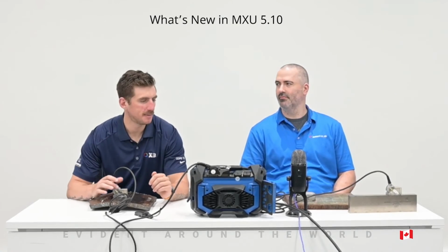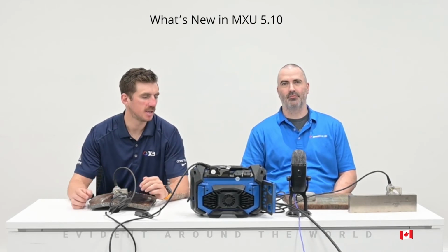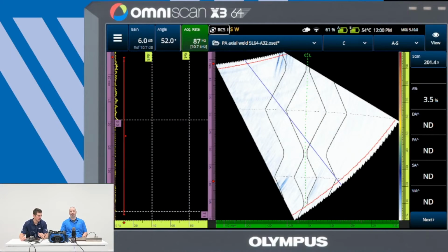Moving to the Omniscan X3 screen, we can see that we have the legs that are shown in our S-scan. But as well as the legs, we also have the weld overlay. Very similar to what we had with a plate before, but each leg is going to adapt the weld overlay so it fits with the sound path of the part. Because as we move deeper into the reflections, the part is not always going to meet the weld at the exact same angle. This is going to make identifying defects a lot easier.